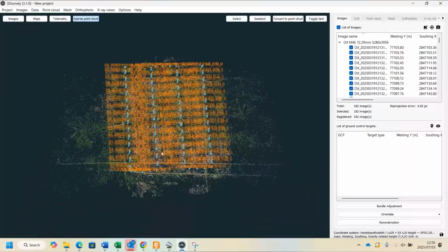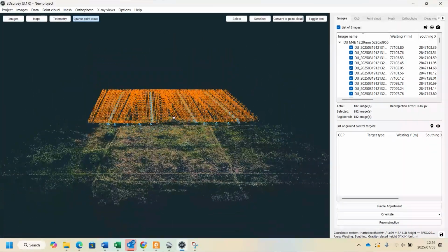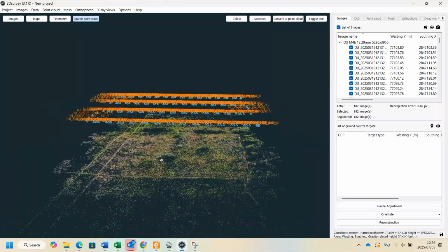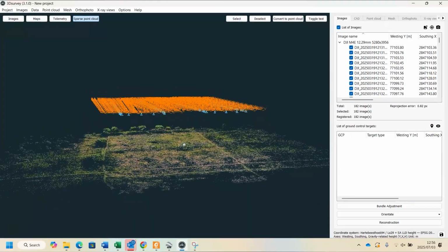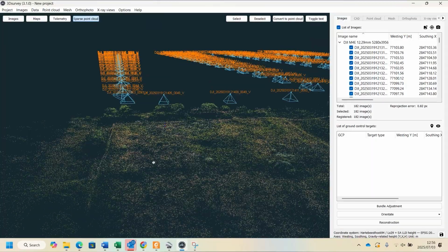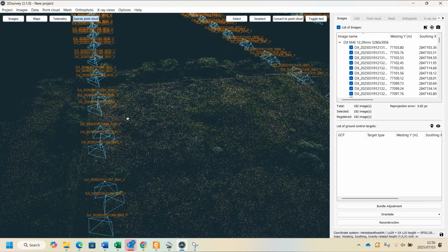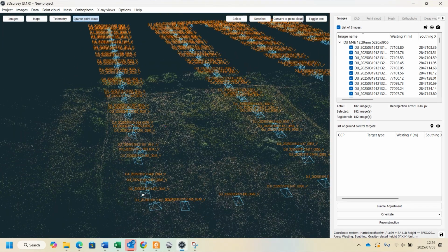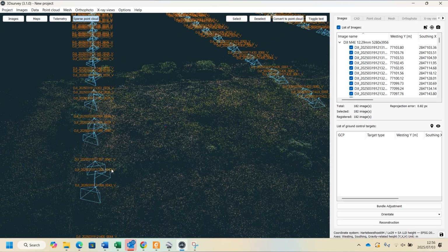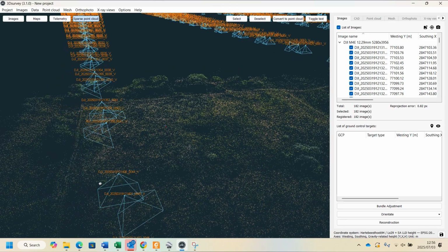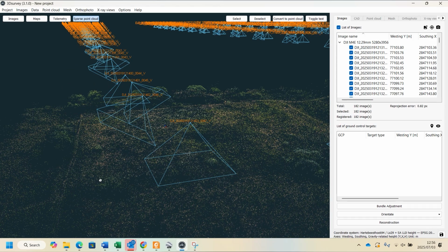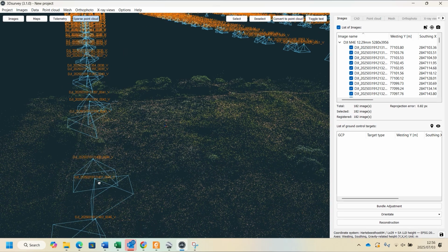Just to give you a little bit of a broader overview, here you can see a bit more of the sample data set that was produced. Alright, and this is actually what I wanted to show you guys. If you look at the way the camera is tilted and angled, we can see that our first camera image is a top down and then a left and a right orientation. I hope I can position this a bit better. So here 3Dsurvey shows you more or less what the angle of the pictures were when they were taken.